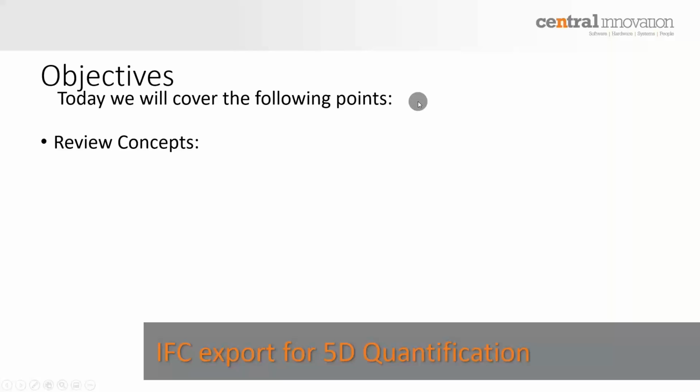Now, I'm going to cover a couple of things. First, I want to review a few concepts. Within those, we want to take a look at what IFC and the specific MVDs are saying for quantification and estimation. Remember that the IFC schema and the MVD, which is a subset of that schema, are the ones that actually will provide you with the best information available within the schema for specific purposes. Therefore, we have model view definitions for design transfer. We have others for coordination and so on. So we'll take a brief look at that and see what is there at the moment.